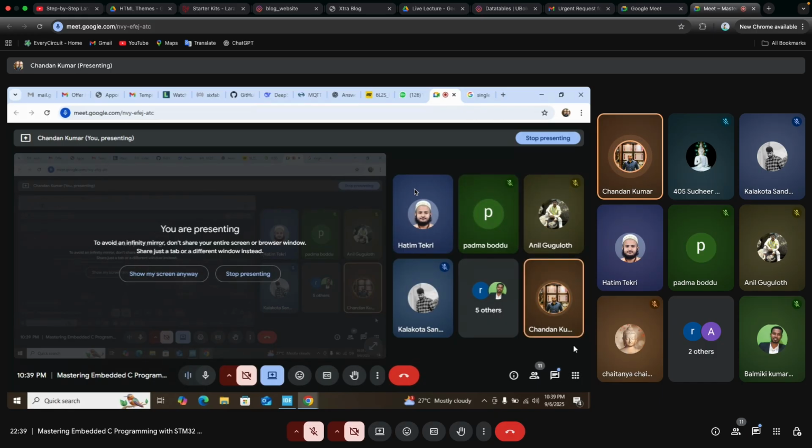So what will happen? The acknowledgement or not acknowledgement bit will be set. It will acknowledge that I have received one bit 4 times, that means it has received 4 bits successfully. But the overall acknowledgement or not acknowledgement bit that gets set or reset when the complete data is received will not acknowledge. Correct?